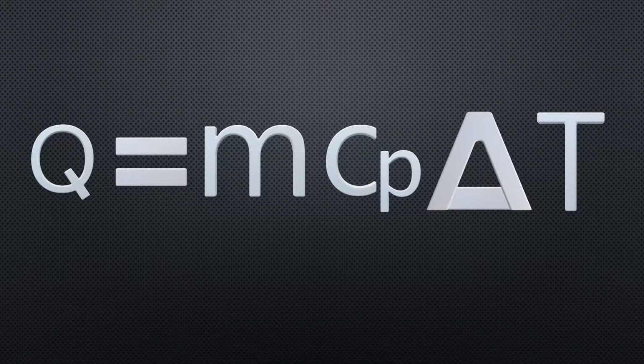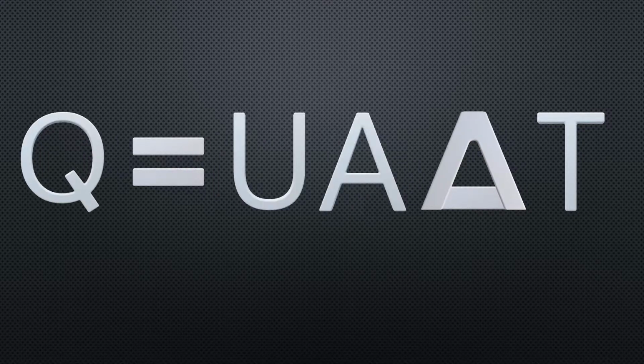It's simple. If you've got more of something, it's harder to heat it all up. And if the material itself reacts less to energy, the same is true. In this case, we need the equation to determine how much energy a fluid needs to gain or lose to achieve the temperature that we want. The other equation to hold on to is Q equals UA delta T. In this case, we're talking about the driving force of energy transfer between the fluids. How much energy you can move from one fluid to the other is mathematically bound by the overall heat transfer coefficient, the area of the interface, and the temperature difference from one fluid to the other at a given point in the system.